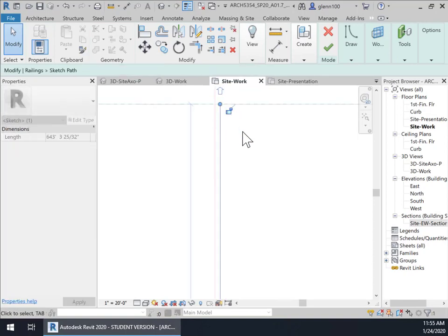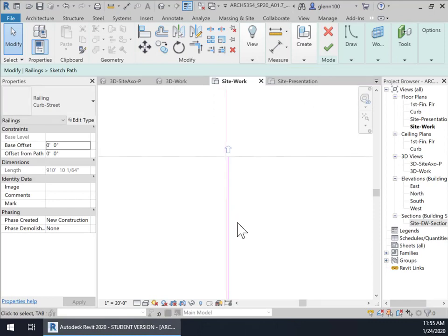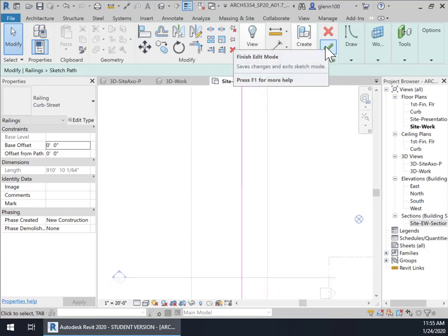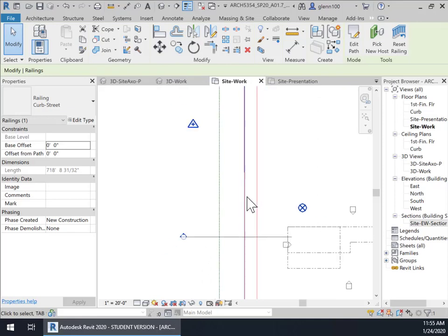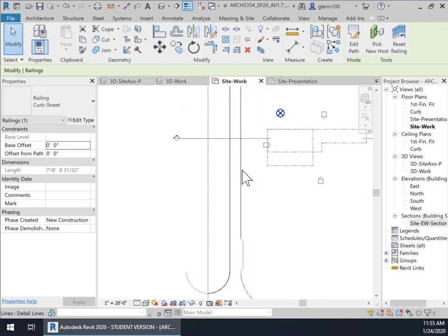Okay. Now you're going to see that it's perpendicular. It lofted it perpendicular, and I'm probably going to have to fix that, and I'll show you how to fix that in just a minute. Okay, so now it's been trimmed. I want you to notice that when I'm selecting that rail, these little lines right up here come up. That flips the profile.